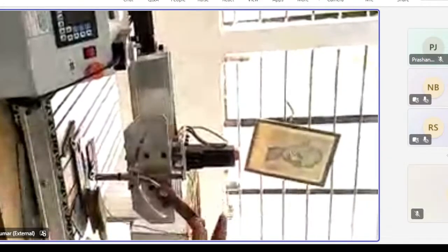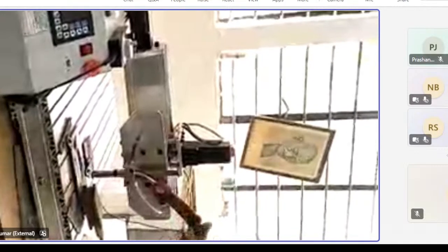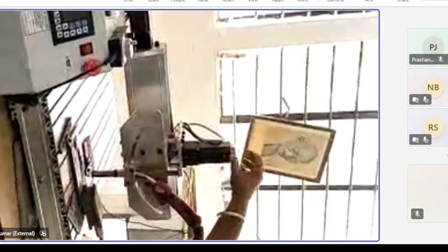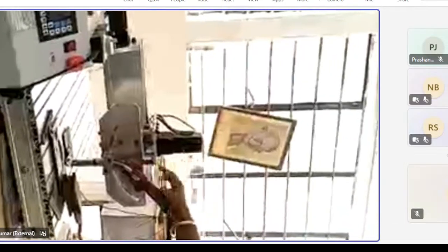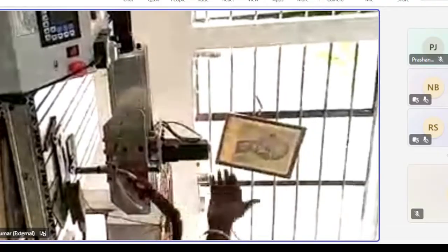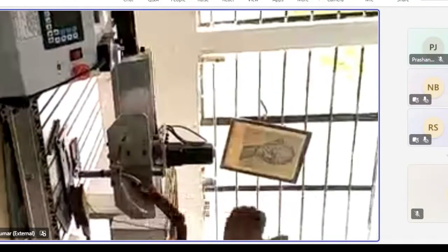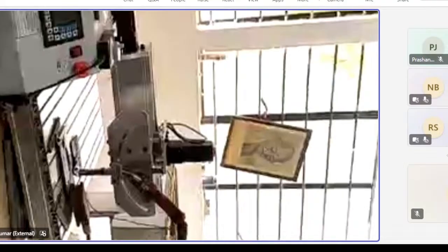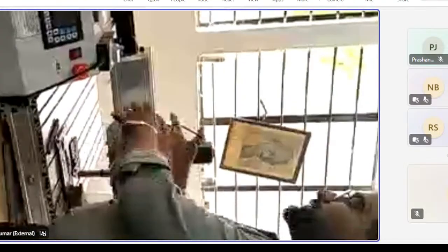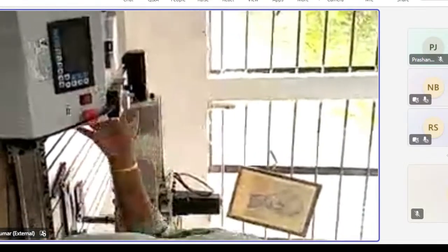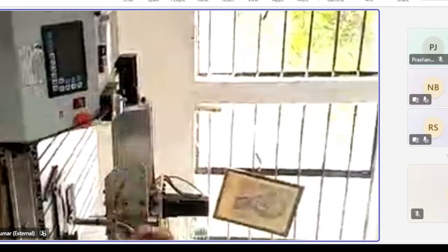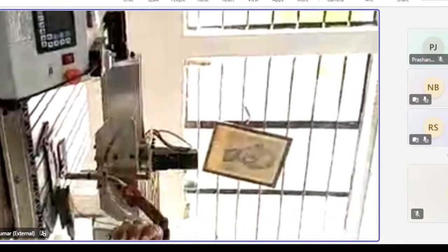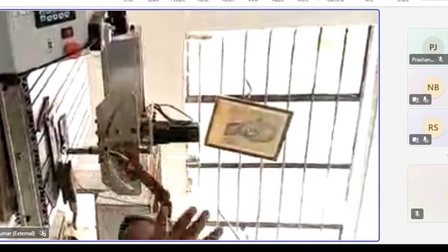This router has three axis control: X, Y, Z. All the control is done with the help of three servo motors, which are attached with a lead screw and ball screw to move in the to and fro direction. This CNC router is connected to the controller through a drag cable, and this controller consists of a number of PLCs and other electronics parts that make it work.